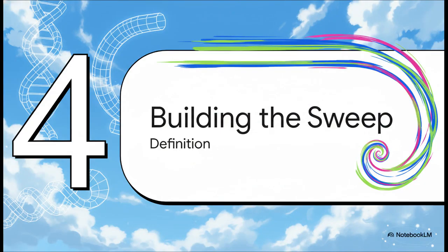So, how do we build our sweep in this new world? Let's start with the absolute workhorse, the sweep one. Seriously, this is one of the most important components to master. It's the go-to method for extruding a shape along any custom path you can dream of. The setup is super straightforward. You drop a sweep one component on your canvas. You create a parameter to pull in your rail curve from Rhino and another one for your section curve. Then you just wire them up and boom, Grasshopper builds the surface for you. It's that simple.